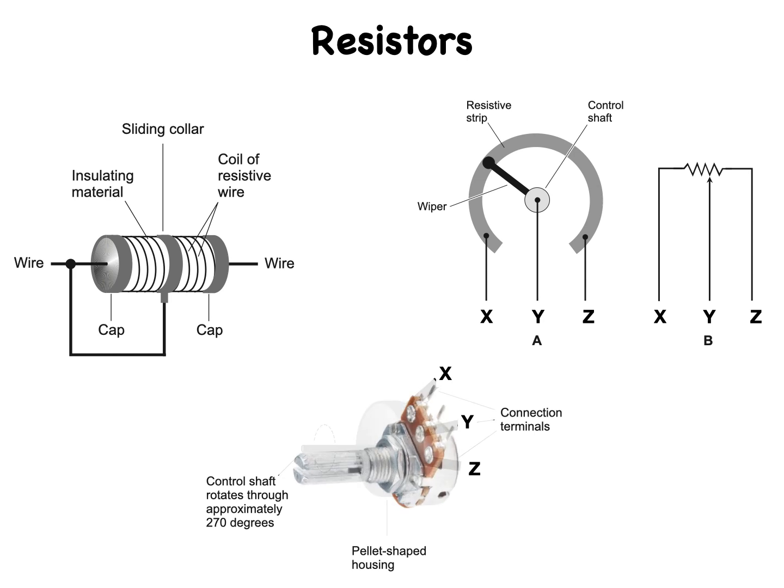Or better yet, the variable resistor shown pictorially can be changed into a rheostat by severing the connection between the collar and the end. Now, the collar can be used as the third or variable contact. Likewise, a rheostat or potentiometer can be turned into a two-lead variable resistor by shorting out the variable contact point with the lead on either end.